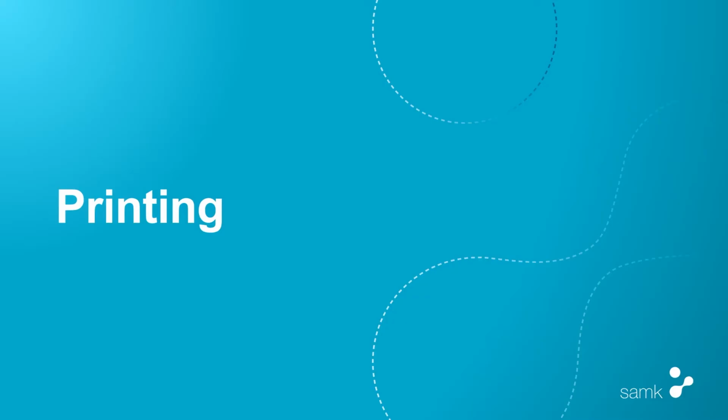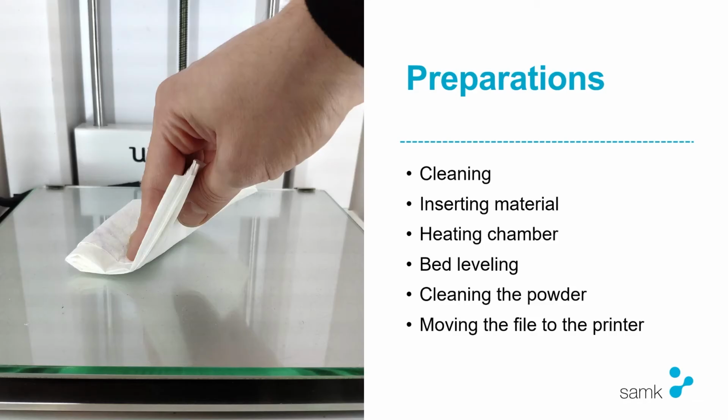So after slicing comes the printing. There are some preparations for this. First of all, cleaning the printer, cleaning the build plate, the heated bed where the print will be formed. Again, we're talking about FDM 3D printing or SLA. You have to check the vat, for example for SLA, if there were any failed prints last time. But if you know that there were no failed prints, you can skip cleaning the vat.